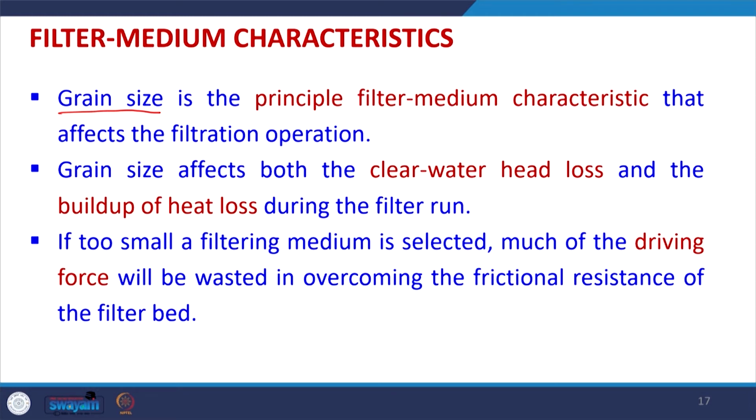Because the porosity of the bed will also be dependent upon that, and what is the pore size. Anything above that pore size will certainly be filtered by the filter medium. But with the deposition of a lot of cake, other smaller size particles will also be filtered. Now, grain size affects both the clear water head loss and the buildup of head loss during the filter run.